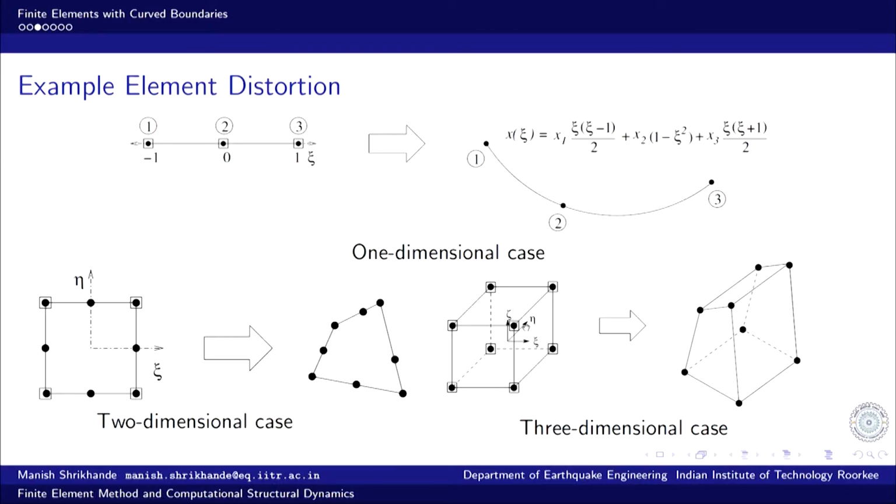So, if interpolation is complete up to second degree, then the first degree interpolation is also included. So, subparametric is of course a subset of isoparametric variation, and this is again an isoparametric variation for 3 dimensional geometry. All 8 nodes are used both for the variation of the primary variable as well as for the geometry.